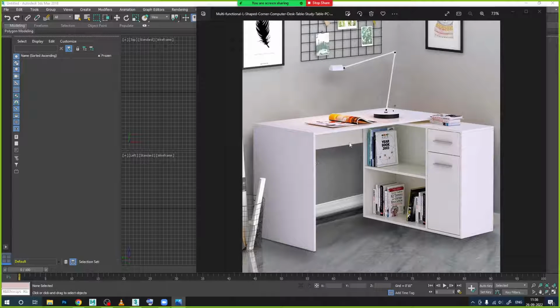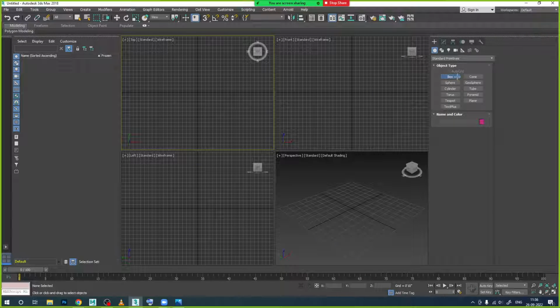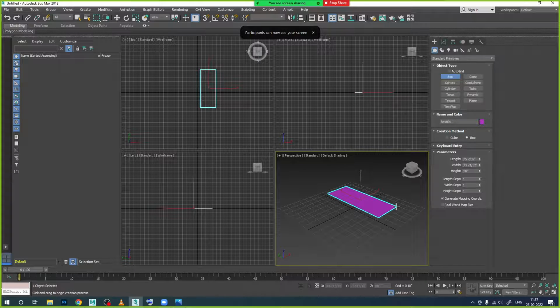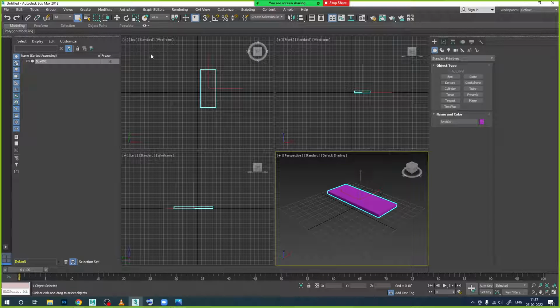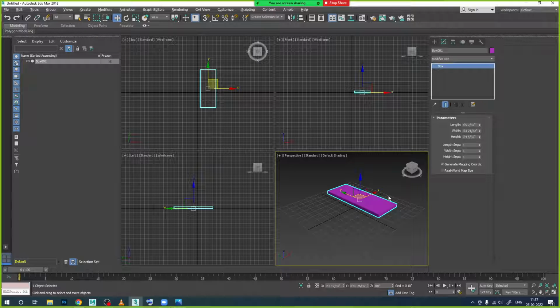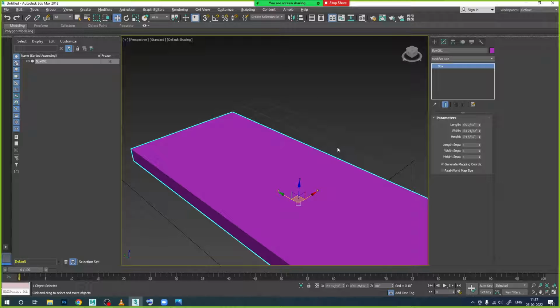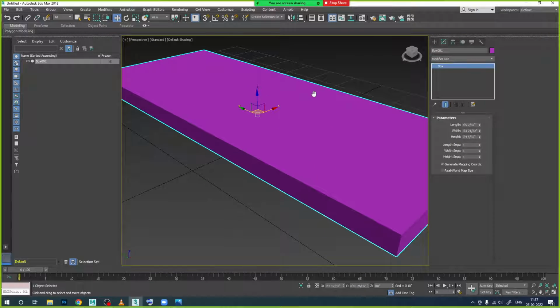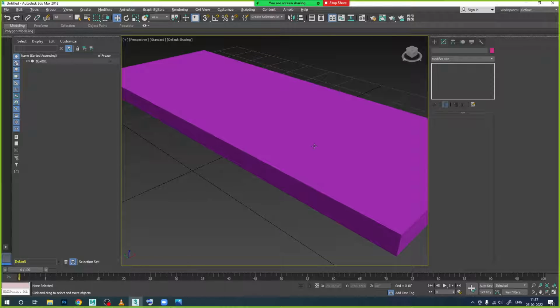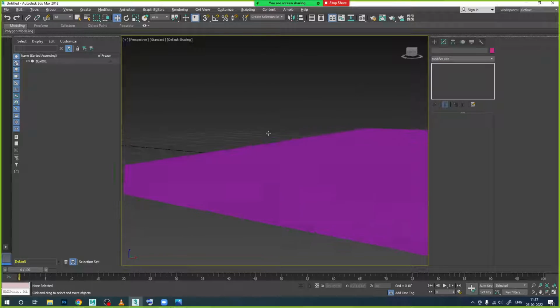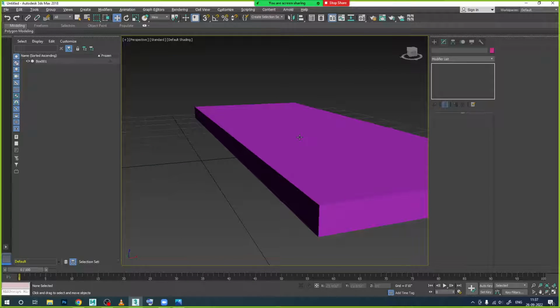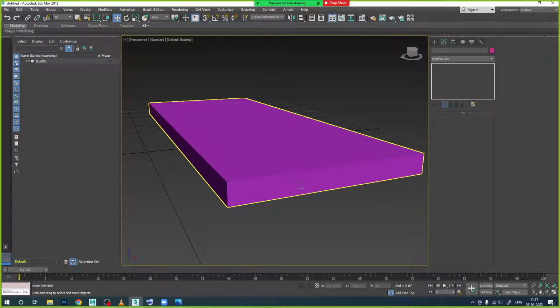Now for example, if I want to build this one, I need a box model. Okay, now create a box model on this area. Release and increase the height for this one. Then right click to discontinue. Now come back and give the properties in this one. Go to the modification option, maximize this viewport by using Alt W, zoom. Okay, and Alt and middle mouse button to pan. Alt and middle mouse button to orbit and see all sides here. Now coming back to this one, select this.